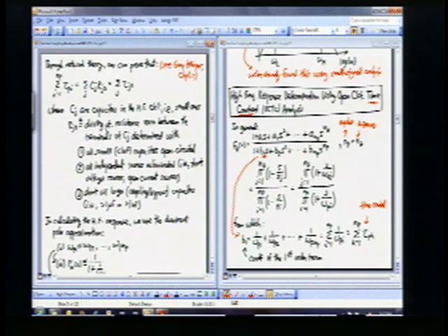Okay. And so if we go back to this here, the definitions for these things are right here. So C sub j are capacitors in the high-frequency circuit, which is basically your small signal circuit that you know how to make, by zeroing out all the DC voltage sources and opening circuit all the DC current sources. The same small signal circuit you've made before, that's which capacitors these are, the CJs.